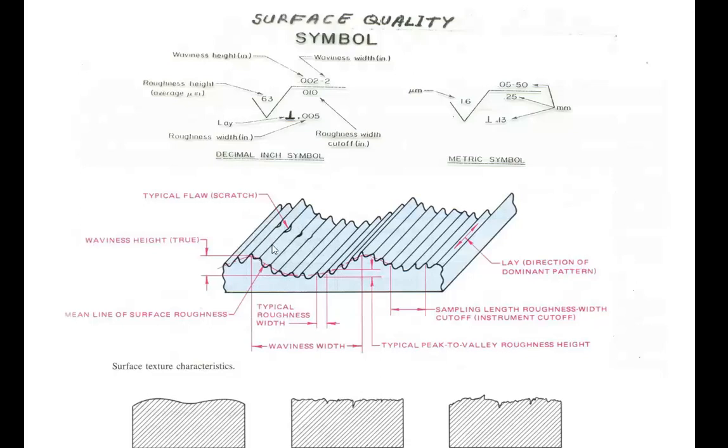Over the surface at a point, roughness may be equal to a certain value, and then at the following place it may be greater or smaller. Since the roughness is not the same over the surface, we need to use average roughness value, average roughness height.